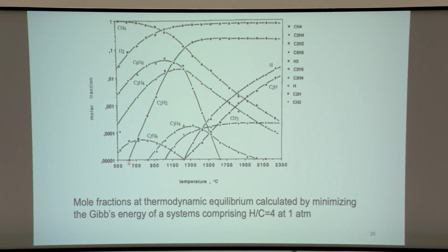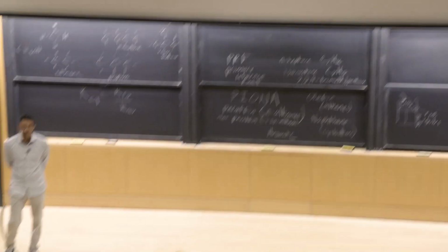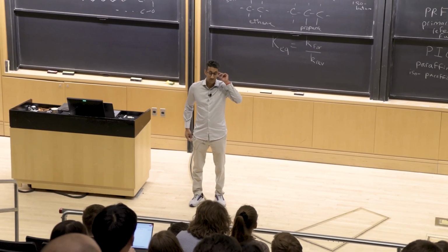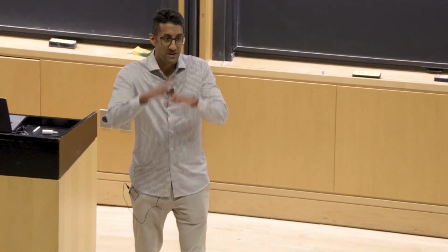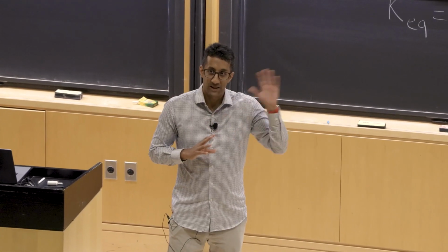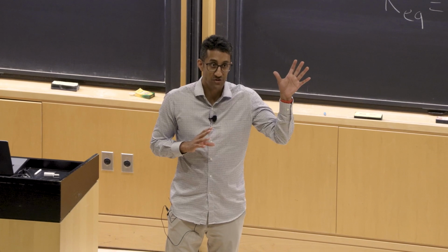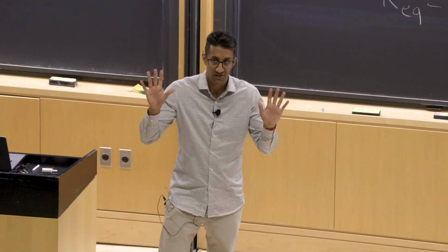And if we heat up this reactor to, say, 1300 degrees Celsius, we can start to form a lot more hydrogen at equilibrium, and methane will be converted to form hydrogen, and its concentration would be decreased. And we use this many times. There's one system that comes to my mind, the pyrolysis of methane. Many of you might have heard of turquoise hydrogen, okay? Turquoise hydrogen is when you take methane and you pyrolyze it, and you want to make preferably elemental carbon and hydrogen. No oxygen, no CO2 formed.